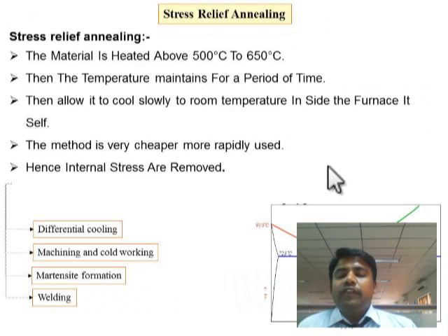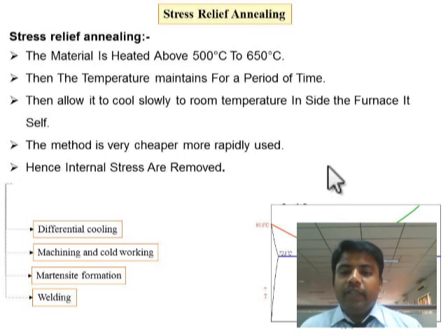Now stress relief annealing. This is done to relieve the internal stress inside your material. This is the third type of heat treatment process. After the material has been made into the part, the material finally goes for the heat treatment process. Here the ductile property of the material is improved, and the internal stress created inside due to the manufacturing process is relieved.